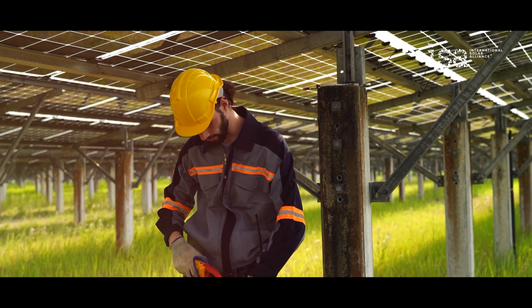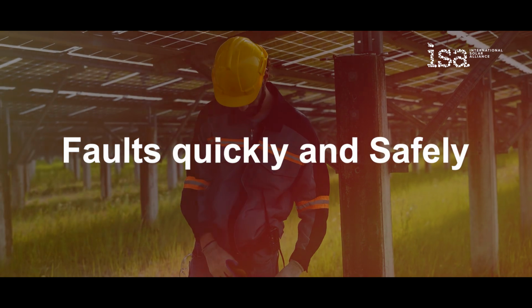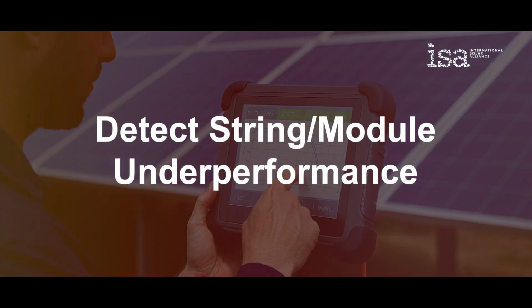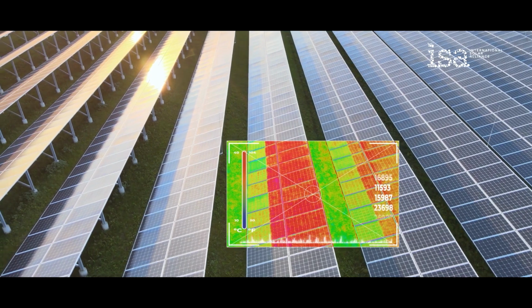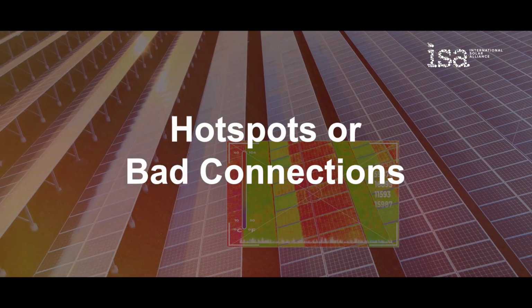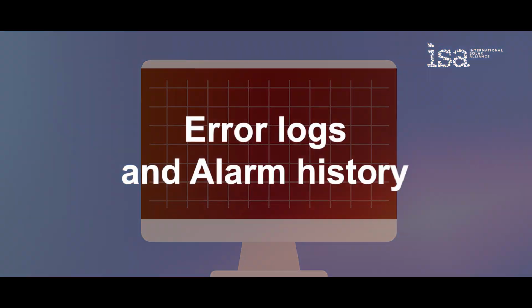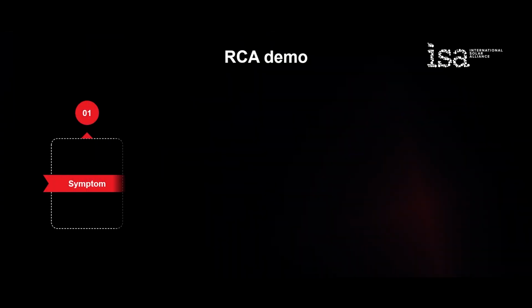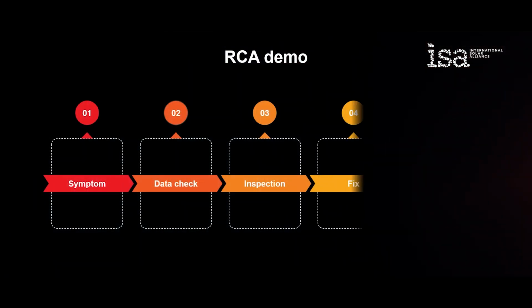Troubleshooting uses data and field tests to locate faults quickly and safely. Use IV curve analysis to detect string/module underperformance. Thermography identifies hotspots or bad connections. Check inverter error logs and alarm history. Carry out root cause analysis, RCA, and failure mode and effects analysis, FMEA, for recurring issues.